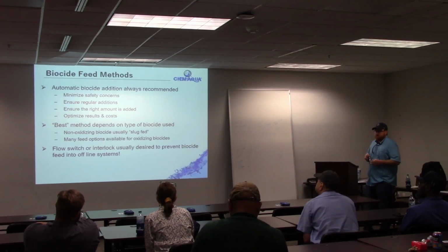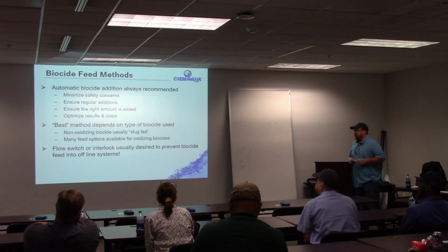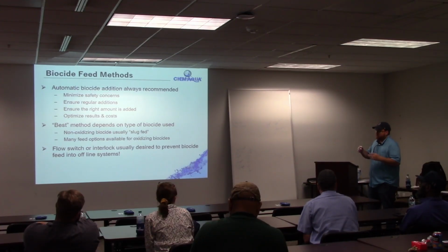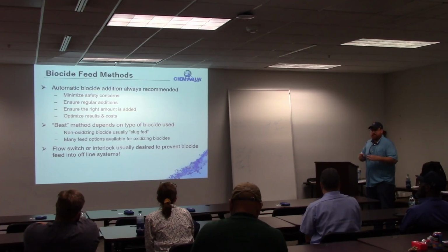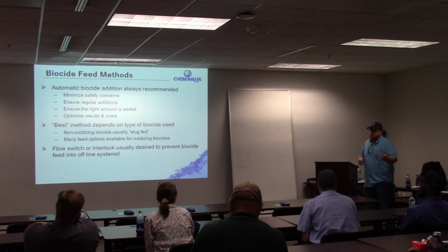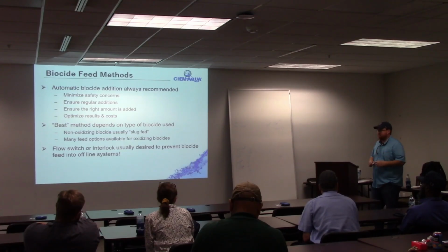Biocide feed is based on system volume. And it needs to also be adjusted based on other variables like how dirty is the cooling tower? When was the last time it was cleaned? Do you have biological issues? Do you have dead legs that are burping?